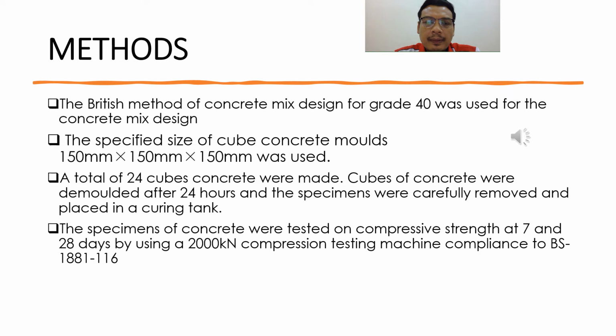This is the method conducted in this research. The British method of concrete mix design for grade 40 was used for the concrete mix design. The specified size of cube concrete mold, 150 times 150 times 150 millimeter, was used. The casting of concrete was done in cube mold measuring 150 millimeter times 150 times 150 millimeter. A total of 24 concrete cubes were made.